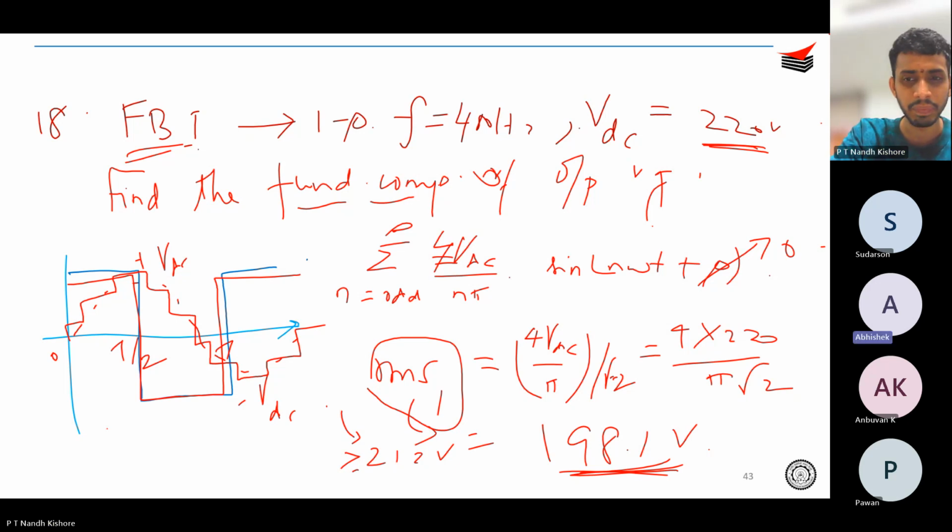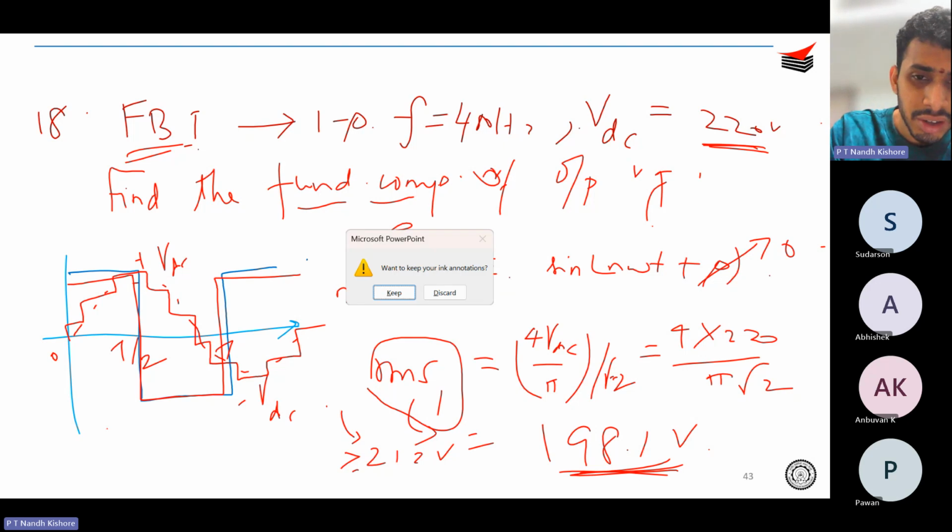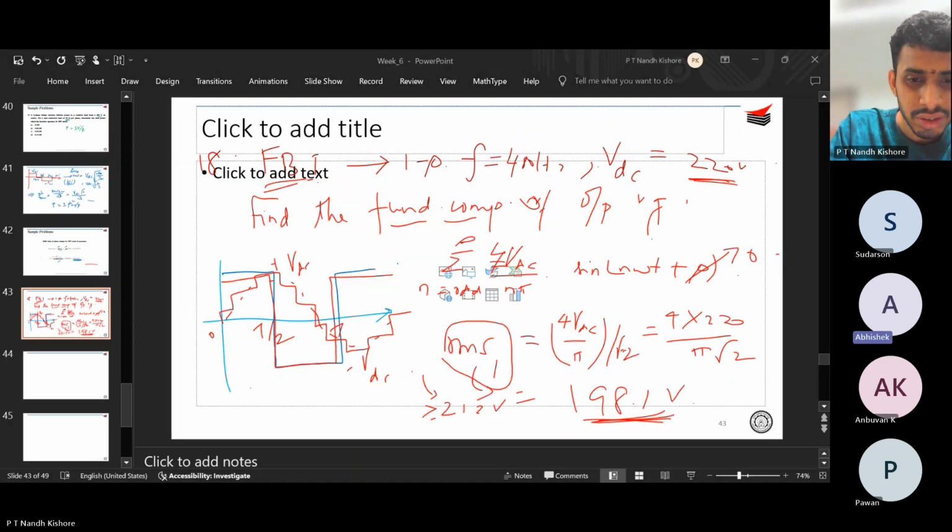In one of the lectures, it's mentioned the linear operating range of PWM is 0.707 or something, so that efficiency of output is lower. To operate the inverter in the linear range, the modulation index has to be less than 0.707.